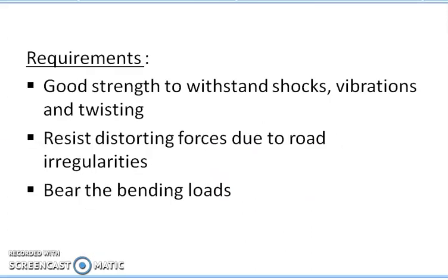So from this, we can come to the conclusion, what are the requirements of a good frame? The frame should have good strength to withstand shocks, vibration and twisting. It should also be capable of resisting the distorting forces due to road irregularities like bumps or potholes, etc. And it should bear the bending loads that are caused due to the weight of the passenger, the various mountings on it, etc. So all these are the requirements of a good frame.